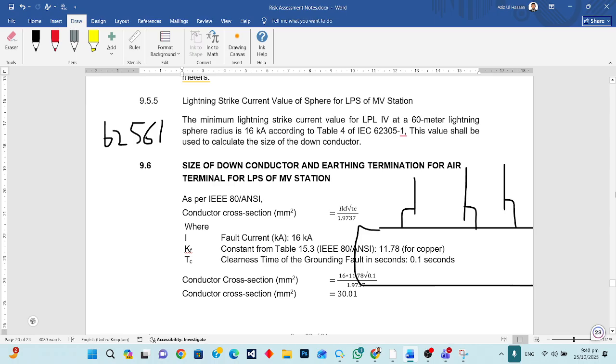But if these specifications are not as per the IEC standard, we have to give a path or conductor connected with the mounting structure. And if the specification is not as per the IEC standard, we can't connect or mount the lightning finials on the mounting structures.